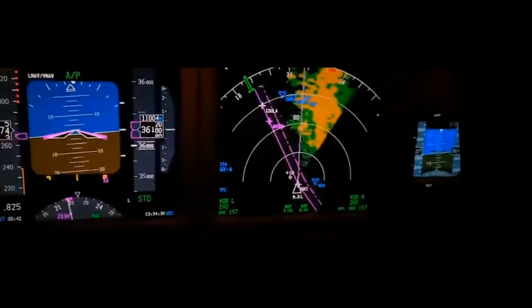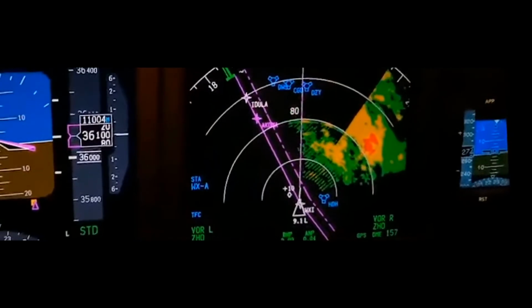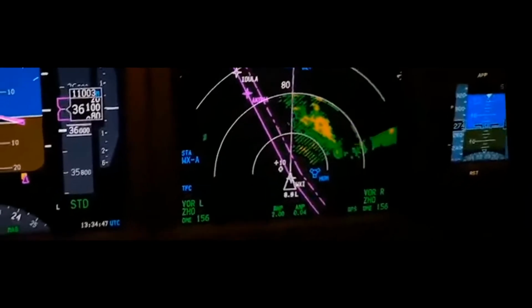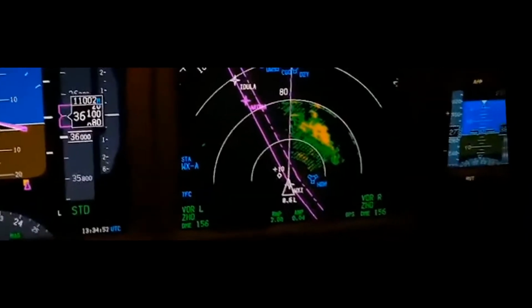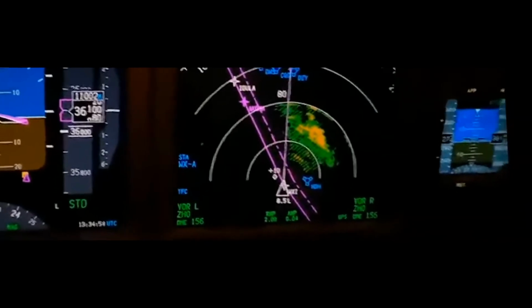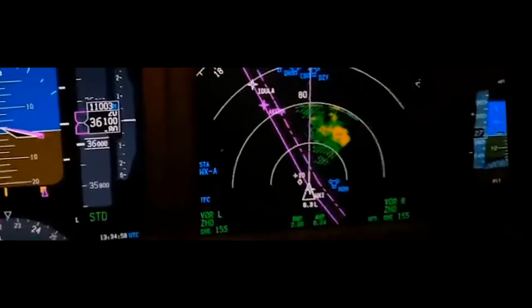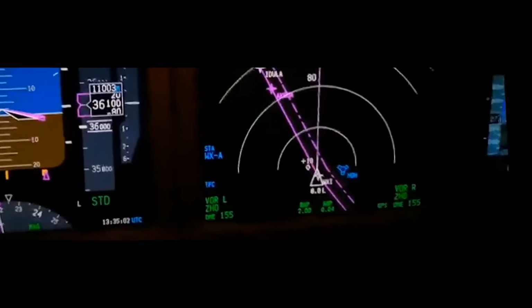This will typically appear on a radar display as a pie-shaped patch and will only be present if there is weather to be shown. However, with newer radar systems like the RDR-4000, the most common cause of spoking comes from the antenna and is caused by noise from the sweep resolver, damaged waveguide, or malfunctioning rotary joint.